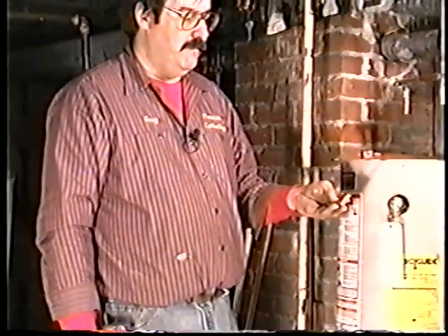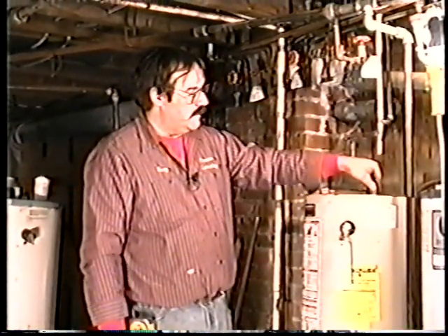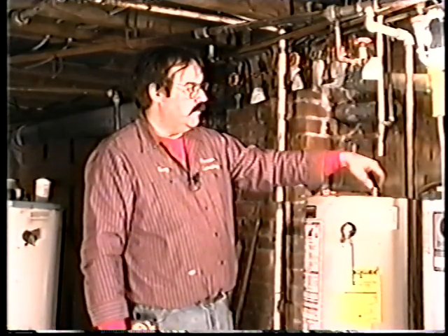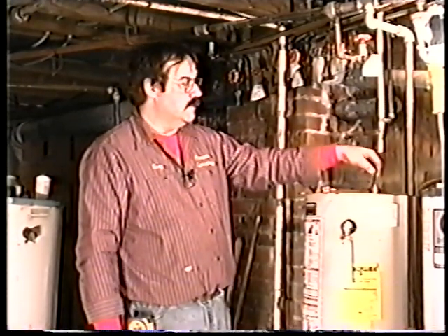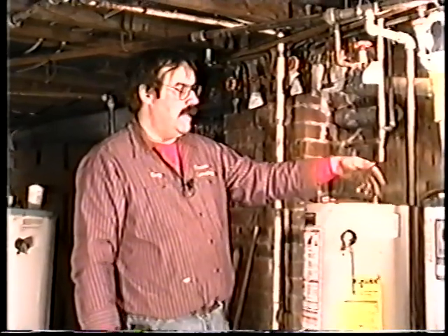First step in connecting the hot and cold water to the water heater is we have to use these fittings called male adapters. They're a threaded fitting by solder. Those will thread ultimately right into the top of the heater. The only thing that you have to be careful of is doing the top solder joint on the heater is not recommended because it melts this connection on the heater.